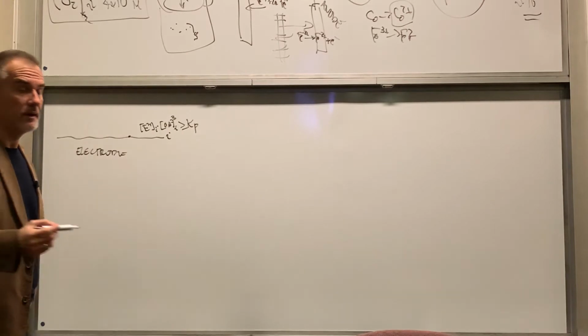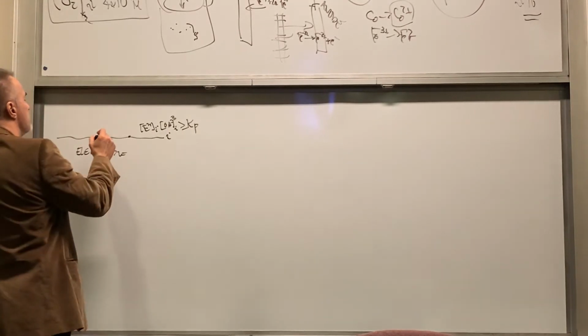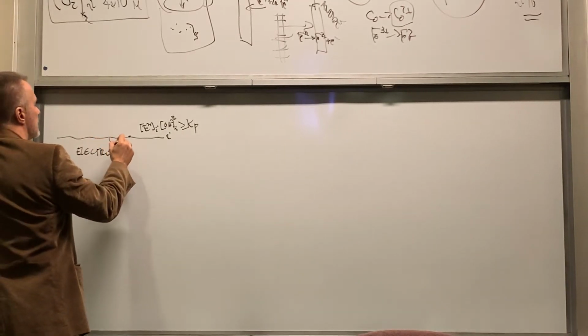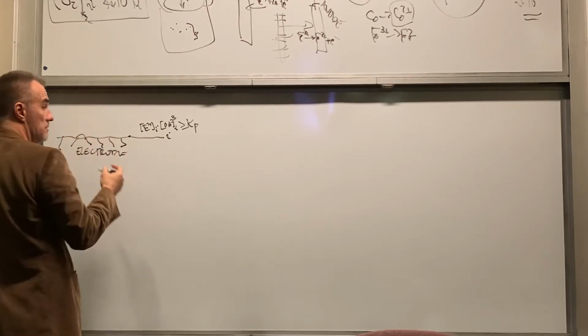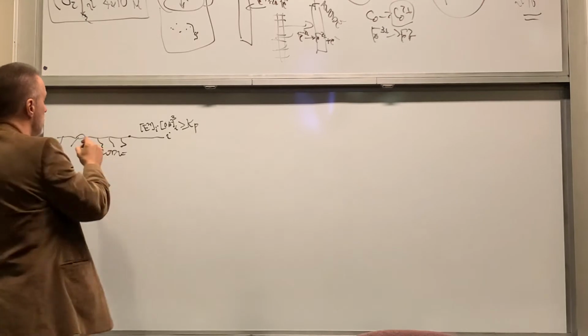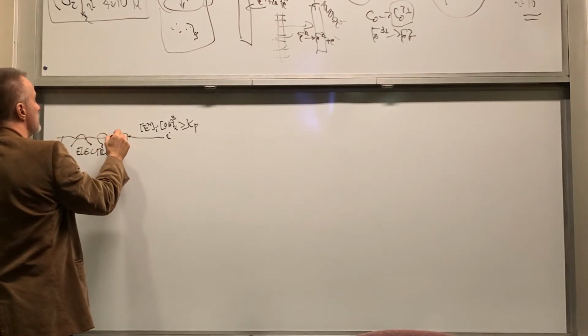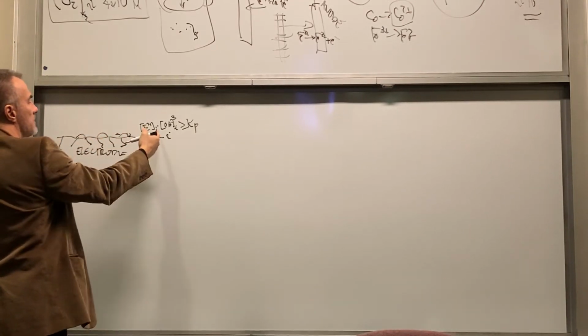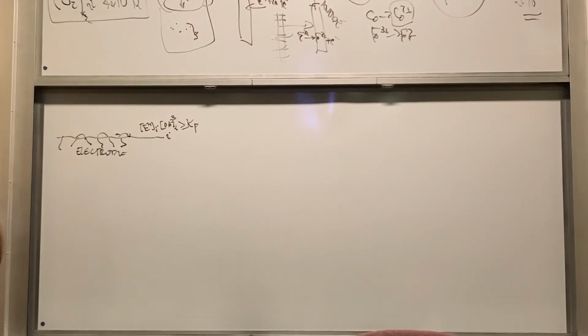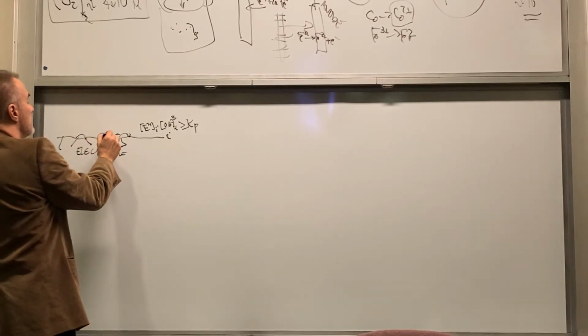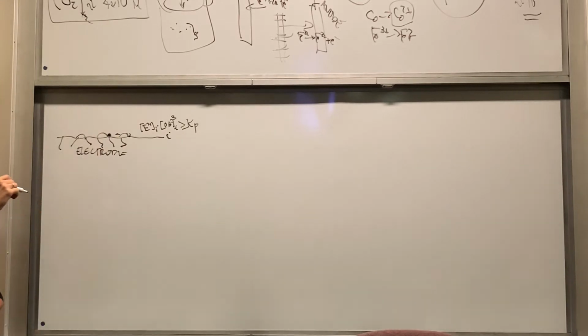So what really happens is that if those are grains, and I'm growing deposits from nucleating here and here and here, and these nuclei grow. Here the grain boundaries, because they are also a convenient place for heterogeneous nucleation, are also going to have nucleation of the oxide phase. A small oxide phase will nucleate here.